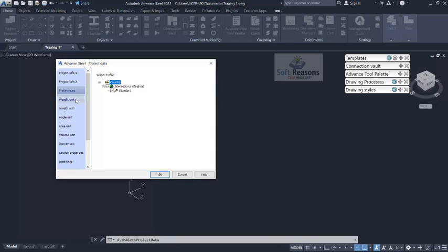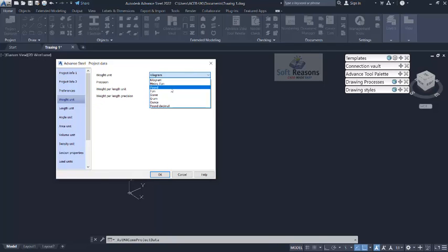The next thing is the unit weight. The unit weight is in kilogram. You can change this to tons, grams, pounds, decimeter, and the rest of that. So here is where you play with your units. At default, when you select international, you have it in metric format template. You can change it to imperial when you get into these provisions. For the precision, we have it in decimal places at default, which you can change in this drop down menu. Your weight per length unit is in kilogram per meter, so you can change it to pounds per foot and the rest of that.